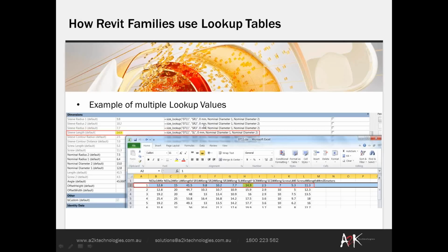It is a little bit different to how some of the other formulas and the syntax and conventions of the formulas work in other areas of Revit, and particularly in other normal family formulas in Revit. It is somewhat a bit backwards, it seems, the way that it's working, where you're looking for a value at the end of this formula, then coming back and referencing that value, then giving it a default. It's kind of on top of itself. So it can be a little bit confusing, but once you've used them a few times, they start to make a bit more sense, okay?